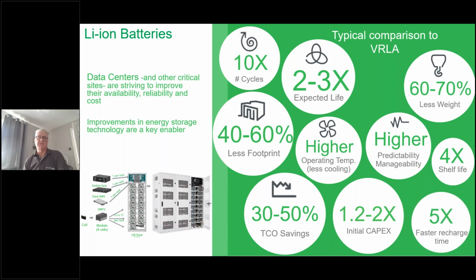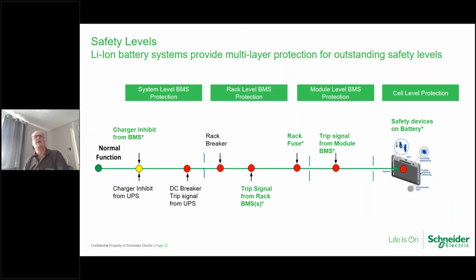And we have a faster recharge time. If we have a battery of a certain runtime, with the UPS sitting behind it, the lithium-ion battery will take more of that recharge power with no effect on the battery, because on a VRLA you have to limit the recharge as the battery won't take it and won't recover. But the lithium-ion battery you can potentially recharge up to 5 times faster. So you don't have an 8-hour recharge to 80%. It could be a lot less than that, 1.5 to 2 hours, depending on the configuration. But that is certainly an element that can be taken into consideration.